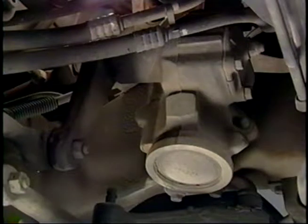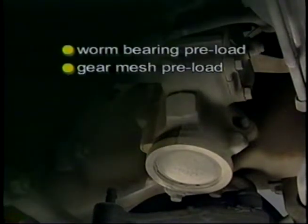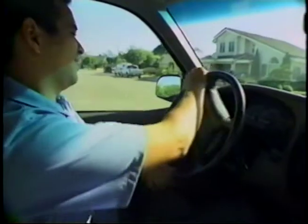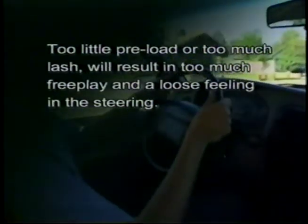There are two common types of steering gears found today: the traditional steering gears, either manual or power-assisted, and manual and power-assisted rack and pinion units. For manual steering units, whether they are the worm and roller type or the recirculating ball type, follow the procedures in the service manuals to adjust worm bearing preload, gear mesh preload, and sector shaft lash when rebuilding the gear unit. When troubleshooting steering gear problems, remember if there is too much preload or too little lash, the steering will feel stiff or tight. Too little preload or too much lash will result in too much free play and a loose feeling in the steering.